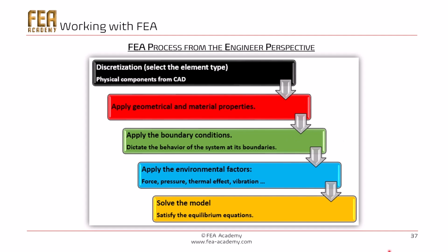Why? Because it's going to dictate the behavior of the system at its boundary, and it will make it solvable by the computer. Then the analyst has to apply the environmental factors, the force, the pressure, the thermal effect, the vibration effects that the system will undergo in reality. And finally, the problem will be solved in order to satisfy the equilibrium equations, and this solving is done by the computer.